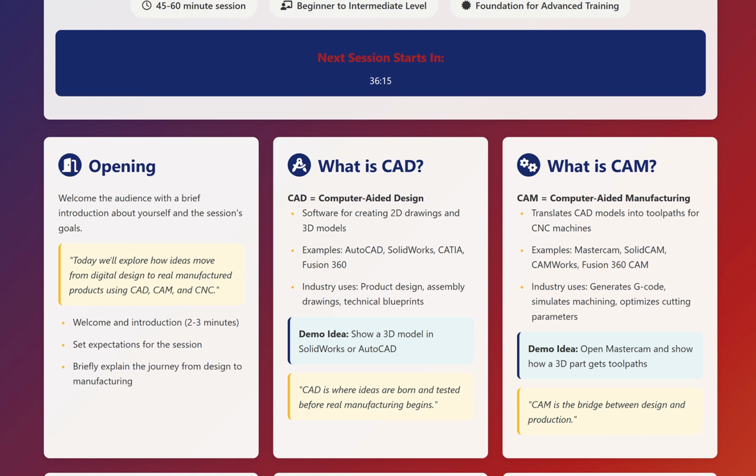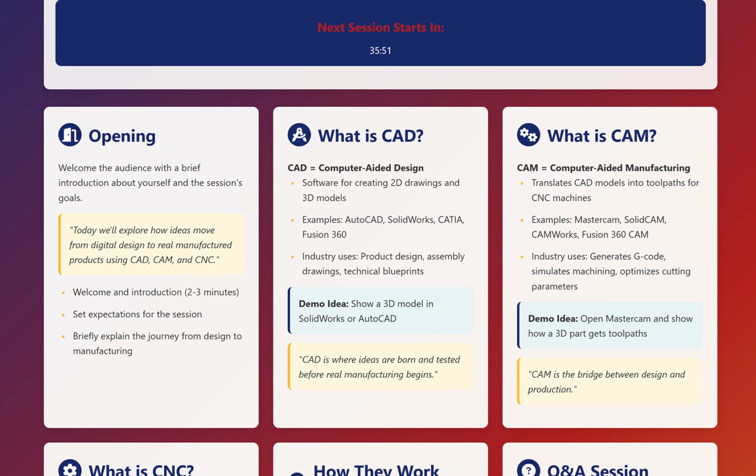That's why you say manufacturing, because there are many ways we can use for manufacturing, like casting, blow mold, injection mold, or welding. Those are many different ways you can do manufacturing. But in our essence as CNC, we use the term subtractive machining. So we will understand how we can translate the CAD models you have into tool paths for CNC machines. Various CNC machines like CNC lathe, CNC milling, CNC wire EDM, CNC router, even CNC water jet.